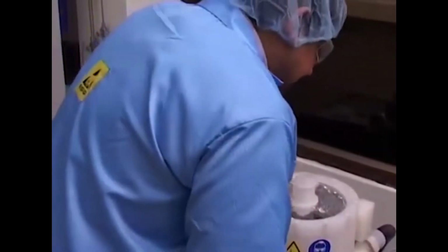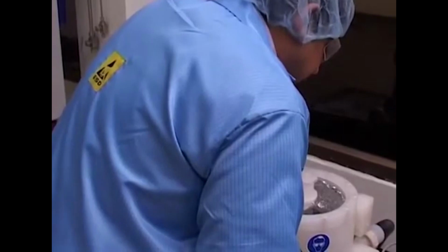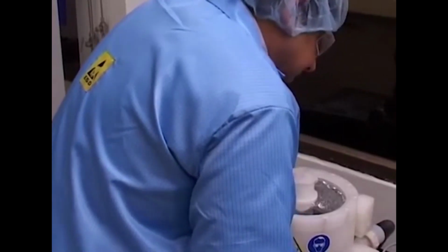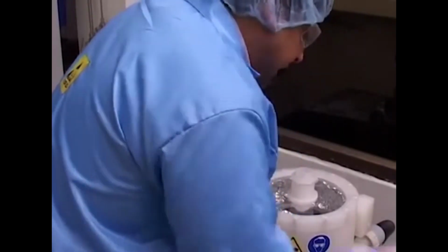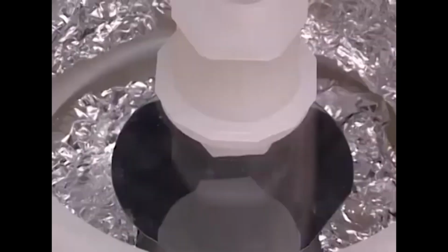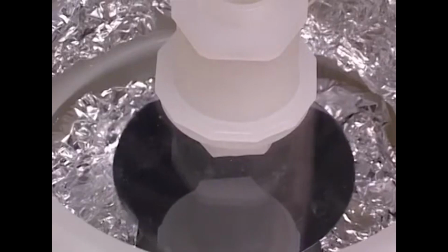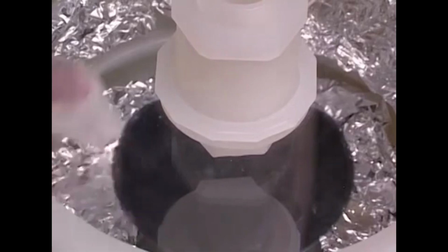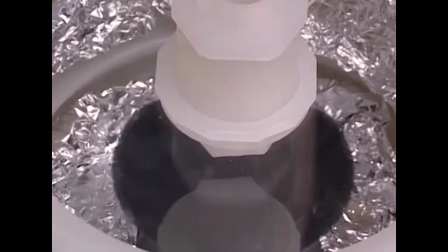Now as I can see here from the top, the wafer is more or less centered, and there is very little wobble. So I really did not do anything about the position of the particular wafer. So I am going to switch this on. You see the wafer is moving inside, spinning, and there is very little wobble, and we can work with this kind of wobble. So I am going to now spin coat the photoresist on the top of this wafer by pouring the resist and then doing all this execution of the RPM cycle.